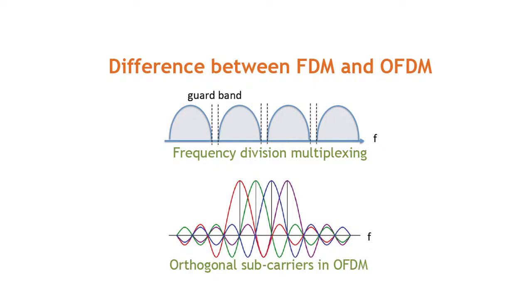So that's why each and every frequency will be separated by the function of the guard band, and from that guard band only, all the data will be transmitted. The same thing, if you go for orthogonal carriers, means there is no guard band at all. All the signals will be mixed at the same time, yet none of the signals will interfere, because each and every signal has its own ID with value, and based on that ID and value, we will be able to apply these subcarriers.